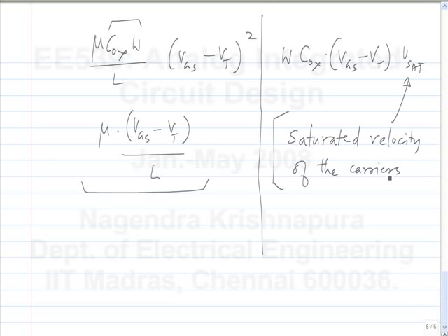Is this okay? So what happens in a regular MOSFET is, as you keep on increasing the VGS in saturation region, the charge density increases and also the voltage across the pinched off channel increases. So the field increases and velocity increases. So both the charge density is larger and they are moving faster. So you get more current. Now in velocity saturated regime, only the charge density is increasing, but the velocity is not increasing. That is fixed. So you get a direct proportion. You get only one VGS minus VT term. That is because of increase in charge density, not because of increase in velocity.